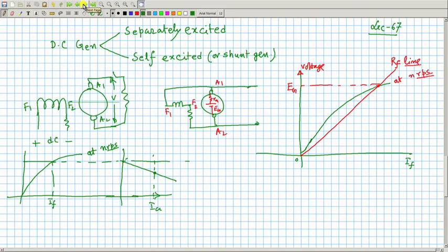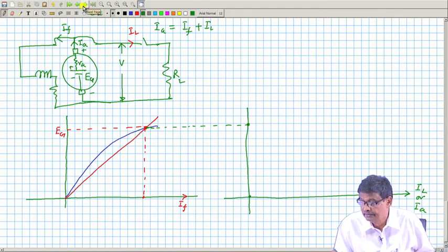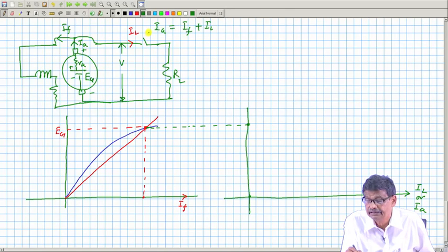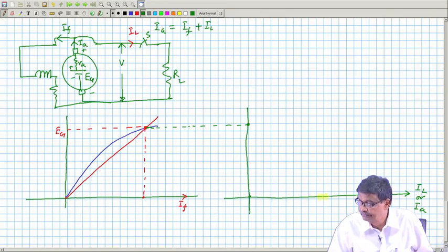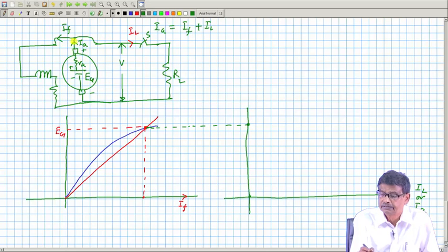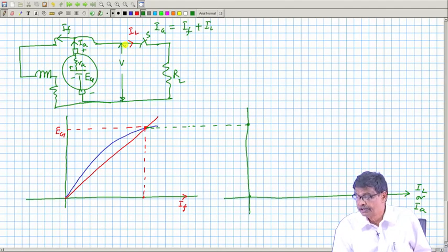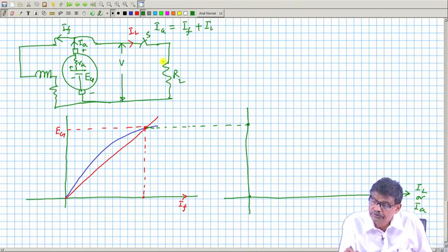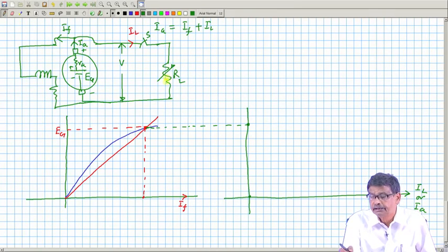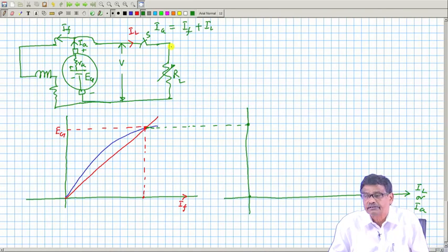Suppose you will connect a load resistance. So, suppose this is the switch, it is connected, armature current is flowing, which cannot now be neglected compared to IL, IA will be of the order of IA, and suppose I make this terminal resistance, load resistance suppose 0, that extreme case let me first tell you.